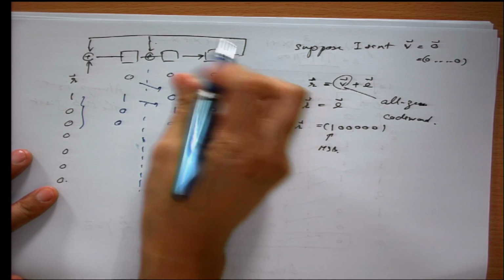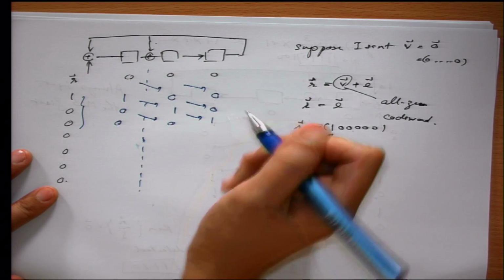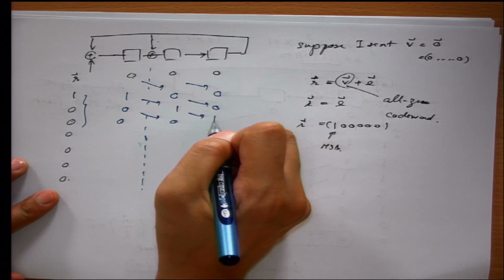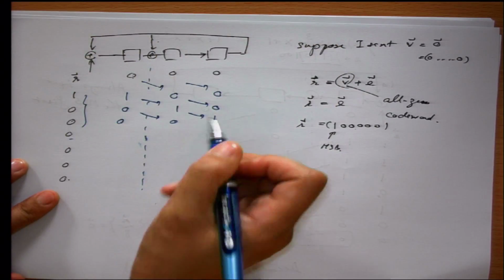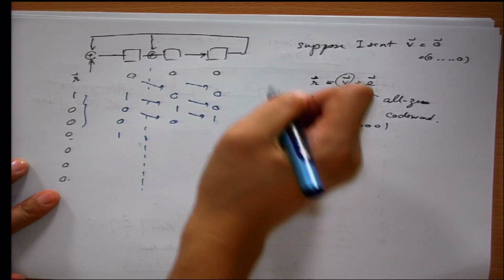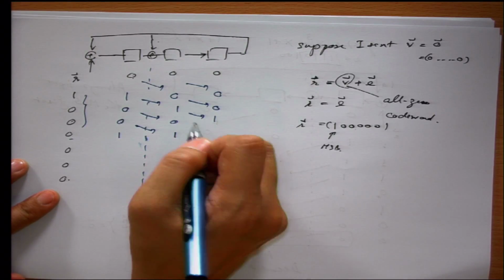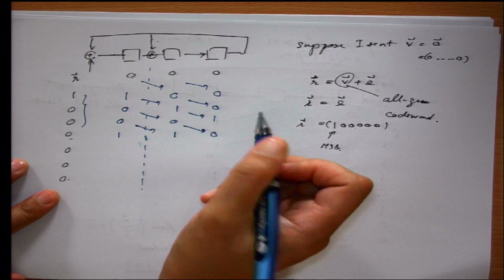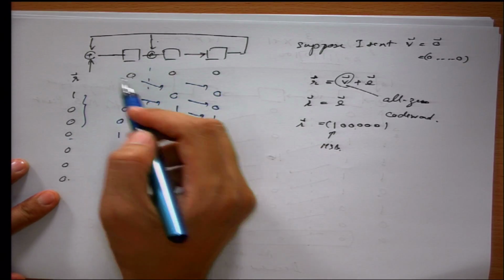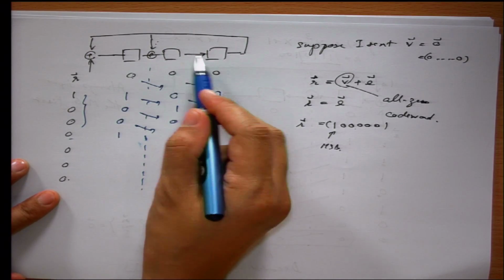So when 0 is put in here, plus 0 is 0, this one shifts to 0, this one is 1. After this, 1 plus 0 is 1, and 1 is the feedback here, so the value here is changed. At this point, 1 plus 0 is 1, 1 feedback here, 1 plus 0 is 1, and 0 is shifted here.